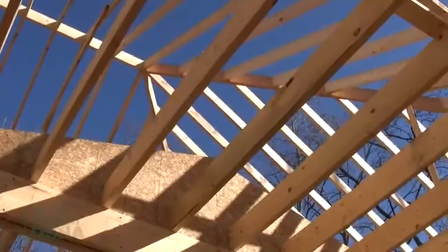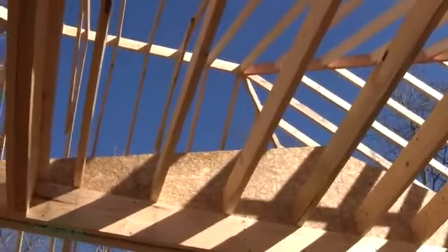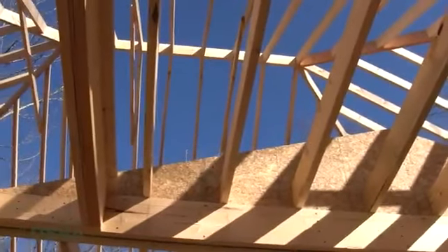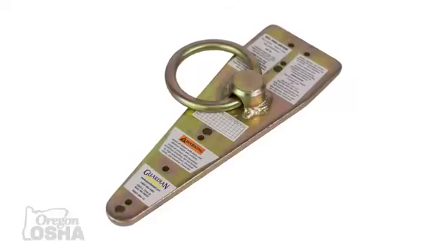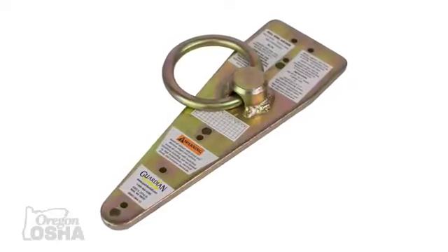One common one we'll see that obviously isn't approved is people wrapping their rope around the peak of the truss, around the rafters. I get that it may handle that weight, but it's not rated for that, and you don't truly know if it will. There's also a leave-in anchor that can be used for the attic, that you basically nail to the side of the peak of the trusses. This provides an anchor point if you're going to be working in the attic or, say, above a stairwell.